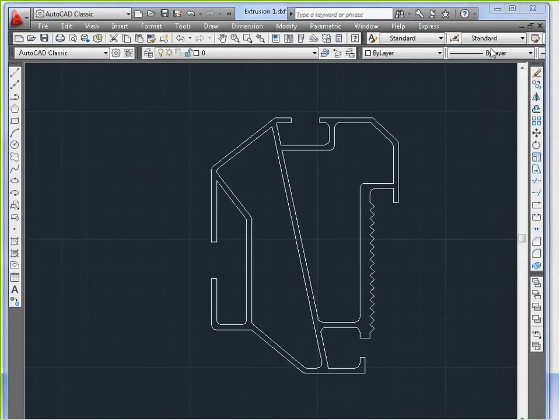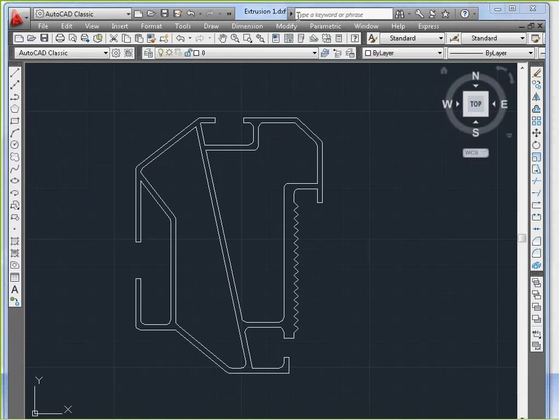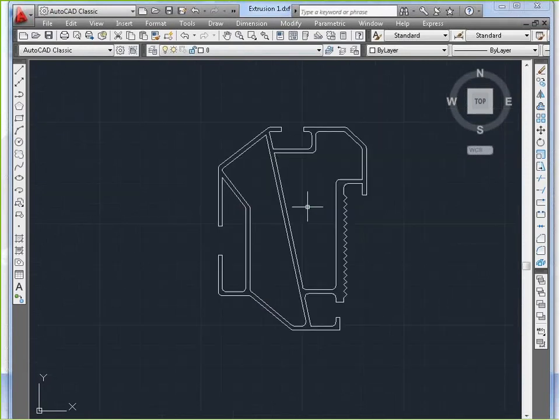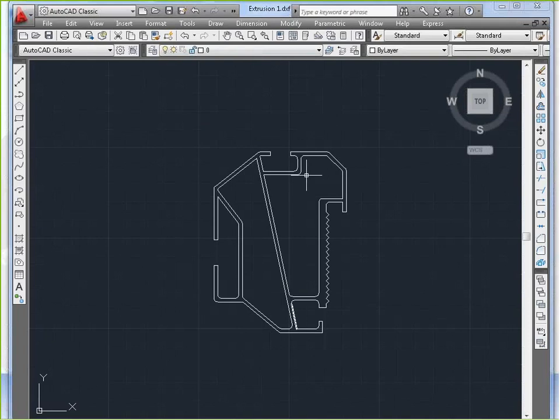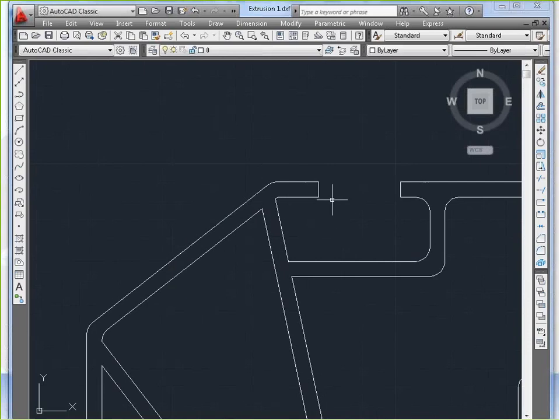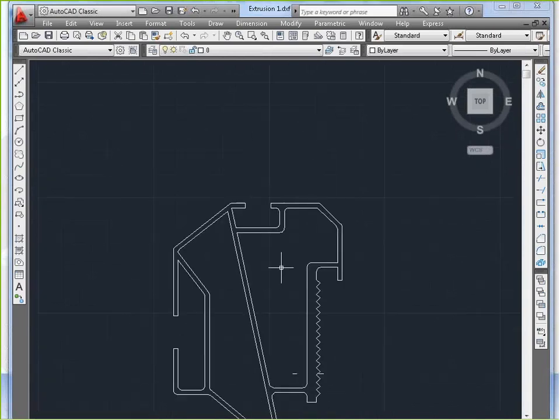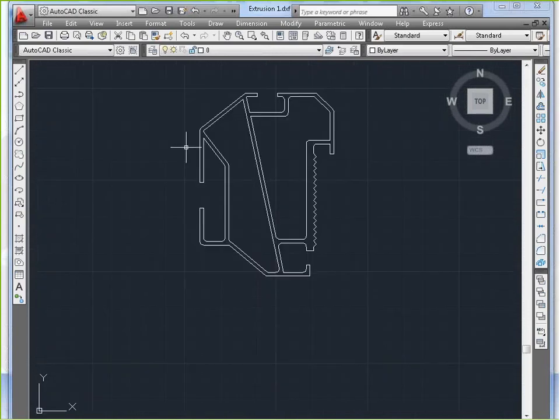Sorry, this is a tight window for my AutoCAD, but we'll start to see that. So this shape is something I built in AutoCAD. It's similar to what a user had requested from us, and I kind of just free-handedly drew it. I think it's more of an extrusion of some sort. But you'll notice it is closed shapes. I did the thickness for everything as a closed shape, and I can import this directly into RISASection.